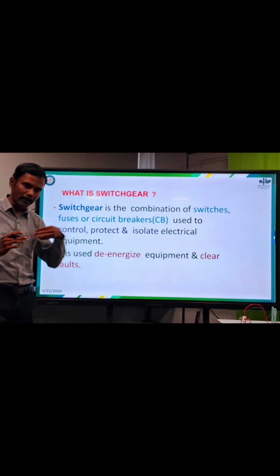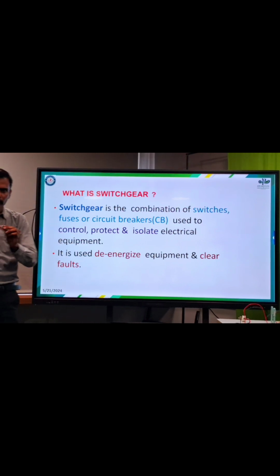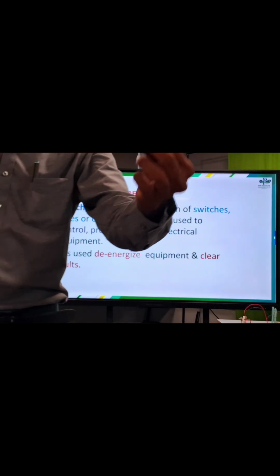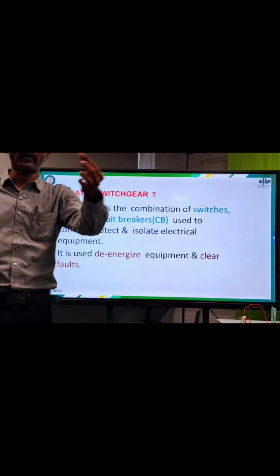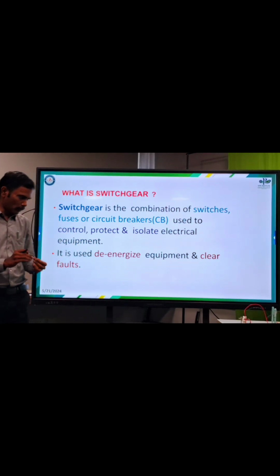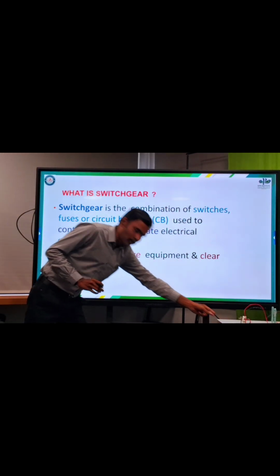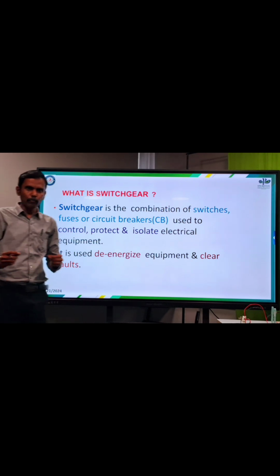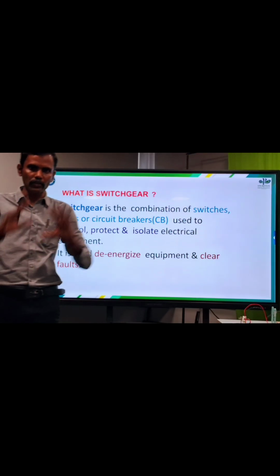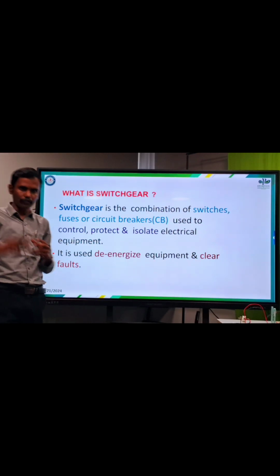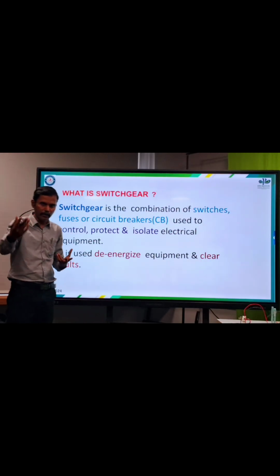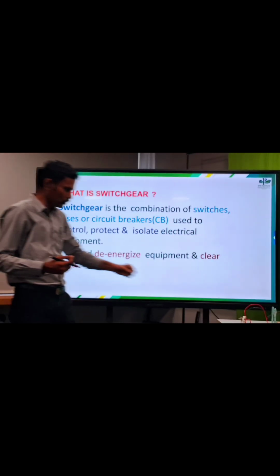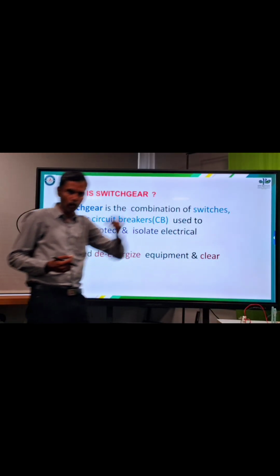Here I can show you one small thing which can be considered a fuse. You can see it in almost all electronic equipment. The fuses play a vital role. When I have a current rating, say for example a motor with a current rating of 12 amps, I can put a fuse of 120% of this total current value. So 120% of 12. It can be maybe like 15 amps. So these fuses, when they get an overcurrent, will be blown.